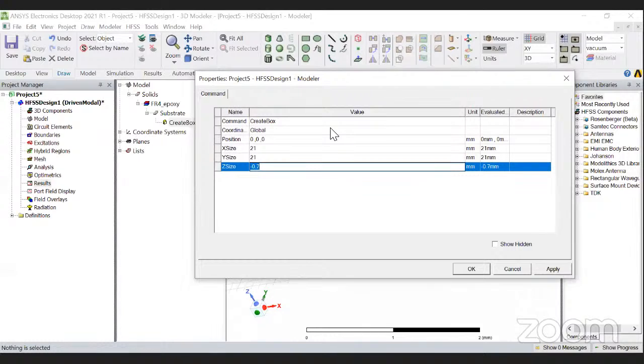This formula is h equal to 0.0606 lambda divided by root epsilon r. Here, the term epsilon r is the permittivity of the particular material. That means the current carrying capacity of the particular dielectric material is called the relative permittivity, denoted in terms of epsilon r. So that's why we put that 4.4 in the formula, and we got 0.158, sorry, 1.58. So approximately I take 1.6 mm. Okay, so 1.6 mm. That's all.